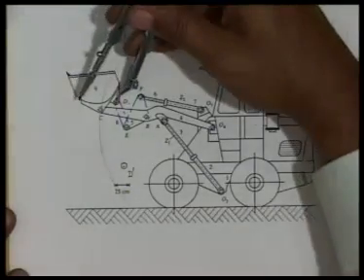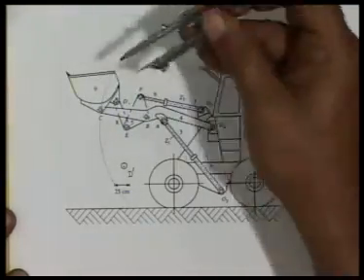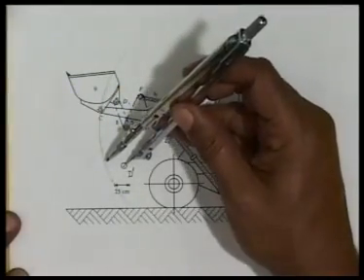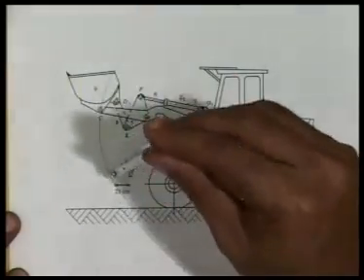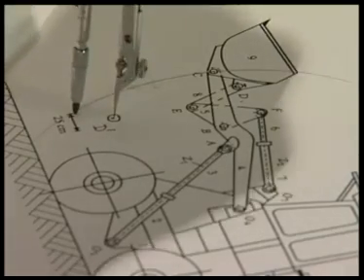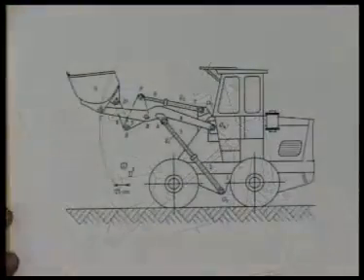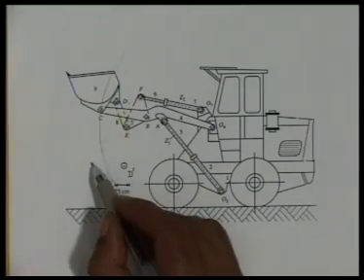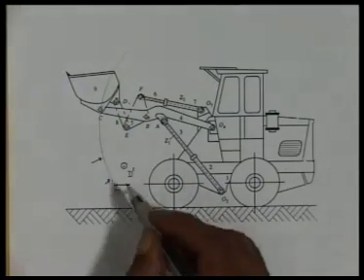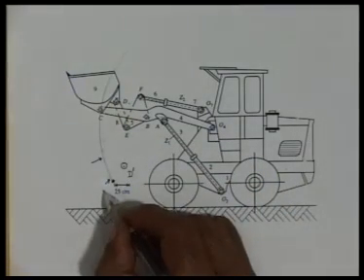Also, D and C being 2 points on the same rigid link, that is number 9, that is the bin, this distance also cannot change. Because I know the location of D1, I put my center of a circle with DC as radius with D1 as the center. If I draw this circular arc, C must lie on this circle. Thus, we get that C should lie on this circle and also on this circle. That means the intersection of these 2 circles determines the location of C. When D moves to D1, C moves to C1.